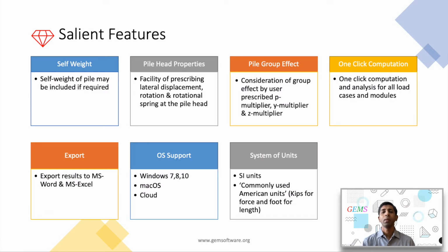Self-weight of the pile may be included if required. There is a facility for prescribing pilehead properties such as lateral displacement, rotation, and rotational spring. One can model pile group effect by user-prescribed P multiplier, Y multiplier, and Z multiplier. One-click computation and analysis of all load cases and modules is available. Computation is available also on a per module basis.